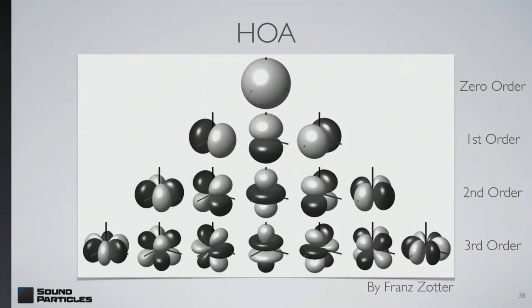And in here, what you see is the Omni component. Then you have these 3 additional audio channels for the first-order Ambisonics, okay? The figure of 8 that you see. And now imagine that you want a more accurate representation. You go for second-order Ambisonics. And now instead of 4, you have 9 channels of audio, okay?